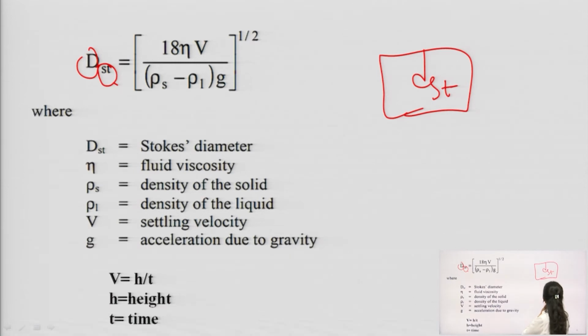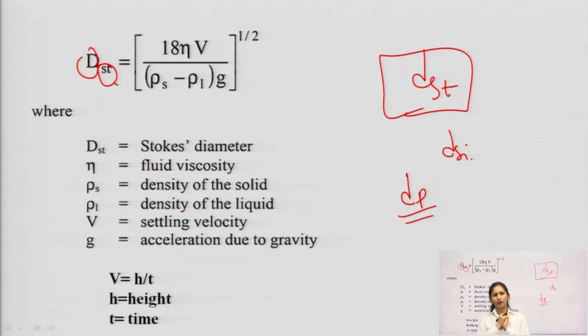And if there is d sieve, then we automatically know, okay, we have determined this particle size by sieving method. If it's a dp, okay, yes, it is an equivalent diameter because it is an asymmetric particle, but to determine the equivalent diameter, what constant parameter did we take, which parameter did we compare with the spherical particle, that is the projected area.